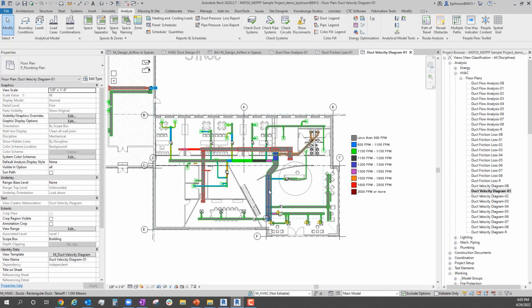So being able to run sizing routines across entire runs after the fact, have it upsize or downsize to the actual size it needs for the CFM and the ductwork would be a great thing to do as the next step, and then see them by color and by range that you actually want to see them, and actually physically change ones that didn't size correctly for whatever reason, weren't connected right, or whatever it might be. Finish with the analysis views to find out what's actually there or not there as you suspect it should be, and then do those final fixes.